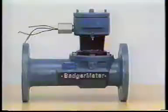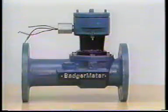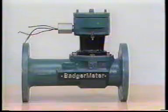Turbine flow meters used for gas service are characterized by a large central hub that is used to create a Venturi effect by decreasing the area in the pipe. This increases the velocity of the gas, providing it with greater momentum to ensure that it will produce enough torque to drive the rotor. In addition, a minimum velocity is required to drive the rotor. This constraint varies with the density of the process fluid. A heavier fluid has greater momentum than a lighter fluid.